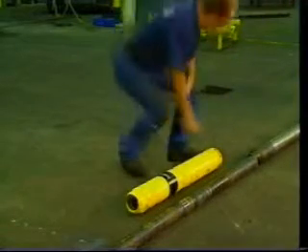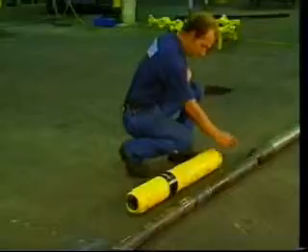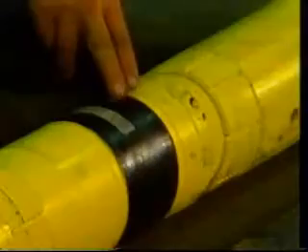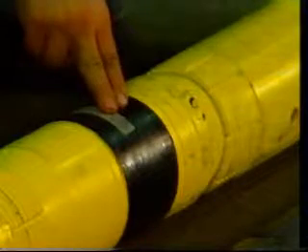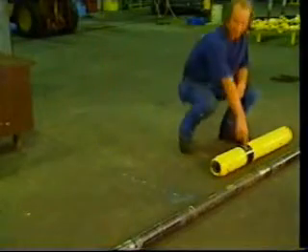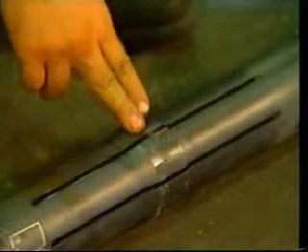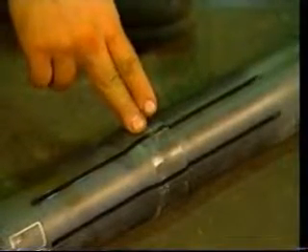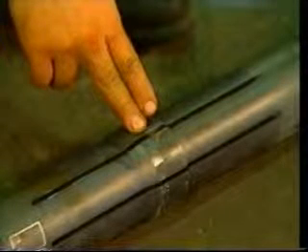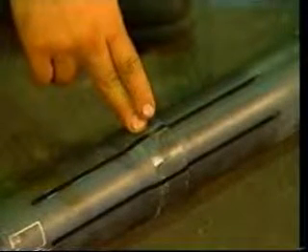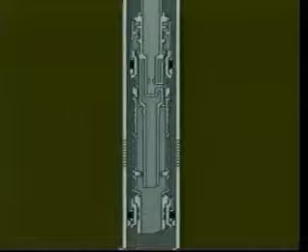Attached to the telltale screen is another crossover sub. The locator and seal assembly are run down to the sump packer, which has been previously installed by wireline. At the bottom of this wash pipe is a multiple-acting indicating collet, which gives a positive indication to the rig hand that the seals are in the sump packer. The tool string is run in and readied for circulation.